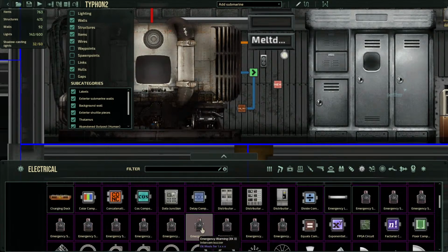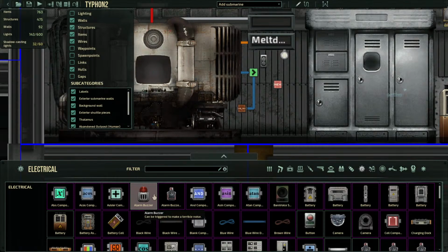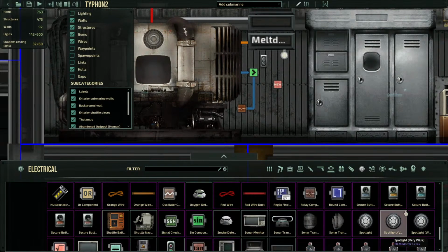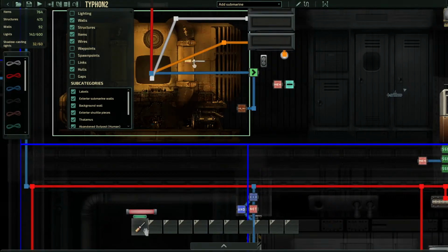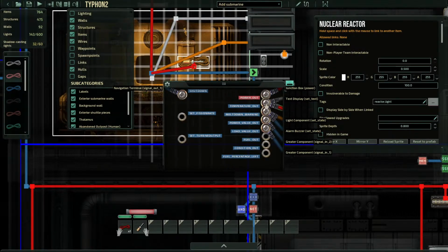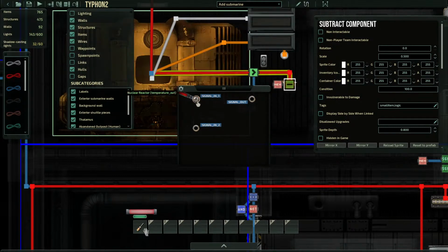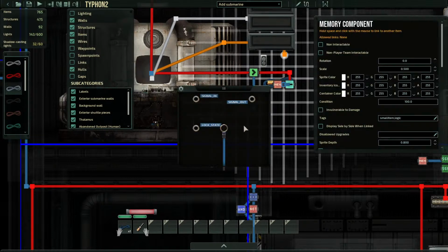That's our target. And we need a subtract block. Where's the subtract? There it is. We're going to take our temperature out and plug it in here. Set point minus value is equal to error, right?